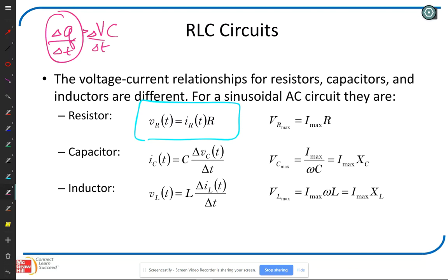multiplied by C. That actually gets us to the words that DJ used when I asked my question earlier, but you said voltage. This equation here agrees with what you were saying. So we have a relationship for the current through a capacitor: it is equal to the capacitance times the rate at which the voltage across the capacitor is changing. If you have a sinusoidal function, doing some calculus, the rate at which the voltage is changing is going to be the angular frequency omega multiplied by cosine of omega t.